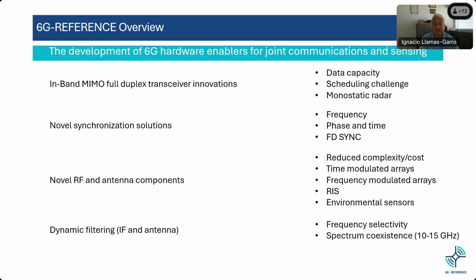Novel synchronization solutions addressing synchronization not only in frequency but also in phase and time. Full duplex synchronization scheme with simultaneous transmit and receive times for all access points to achieve super resolution. We also address novel RF and antenna components focused on reduced complexity and cost, including time-modulated arrays for simultaneous parallel multi-beam reception and transmission with low-complexity single RF chain hardware.